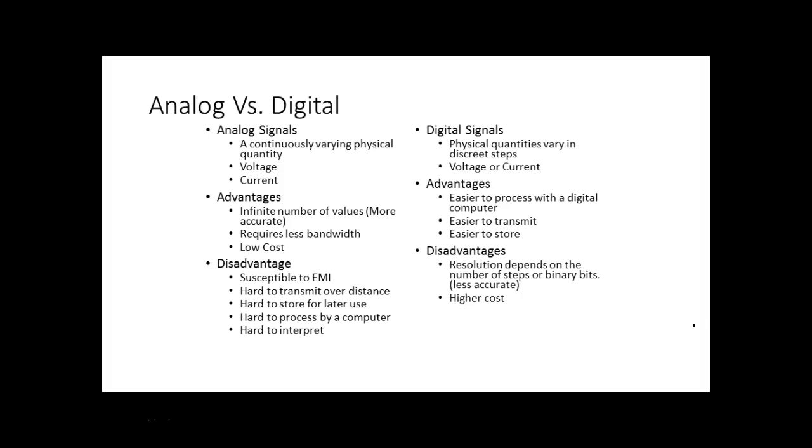So what we have to do is start adding more of what we call bits. If I had 8 bits, I could only transmit 256 different levels. That makes sense? If I had 10 bits, that would still only be 1,024 different levels. But in analog, I could do an infinite number with just 0 to 5 volts. So we start adding all these bits so we can get better resolution.